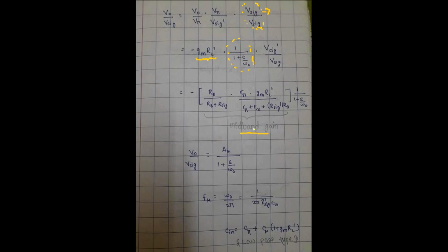On the Bode plot, there was a certain region here. The height here was 20 log AM. So the AM here is what midband gain is. To find out the voltage gain for the midband, you just have to take 20 log of it. And this midband gain is the region where your voltage amplification is optimal because no capacitances are in effect, and it lets the voltage amplification take place smoothly.